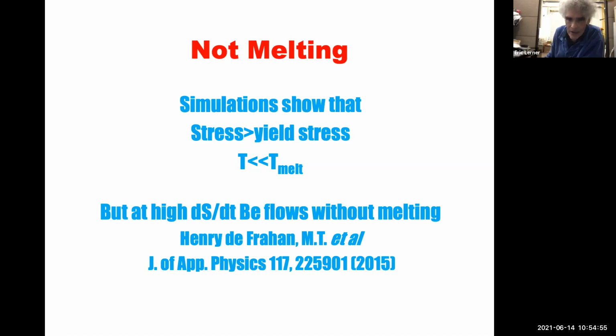The solid beryllium flows like a liquid without melting. So this is a very convenient and very interesting property that was discovered only recently in 2015 using explosives, actually, as the source of the sudden stress. And our stress onset is just in the range that they were looking at. So our interpretation is that the beryllium was actually relieving its stress by doing this rippling.